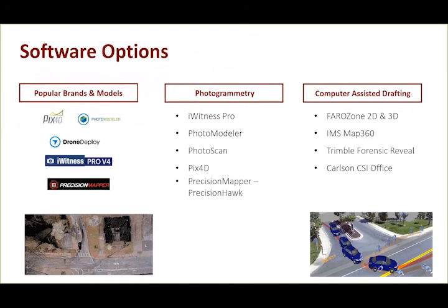For example, like someone asked before, for photograph overlay, Pix4D's might be different from PhotoModeler, so you have to be aware how you're going to fly those grid patterns and what percentage you're going to get for the side overlap as well as the frontal overlap of those photos. Because if you're not flying to what the software requires, you're going to have a pretty poor final product.